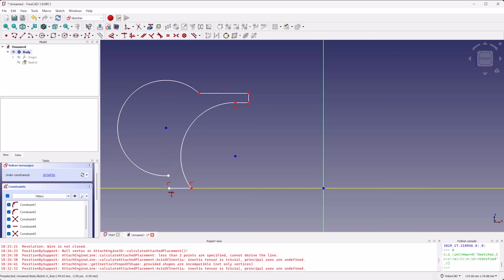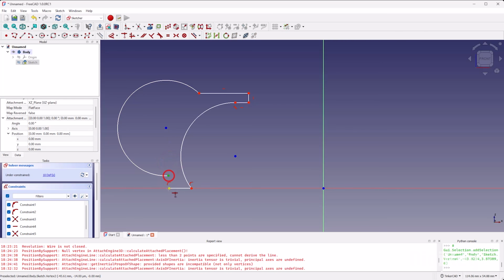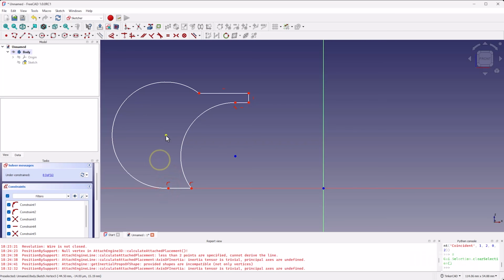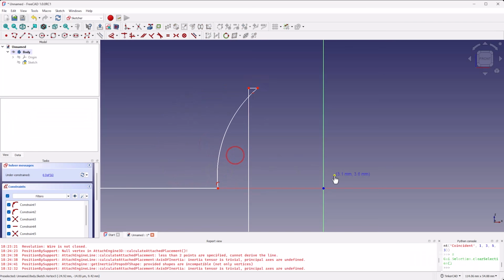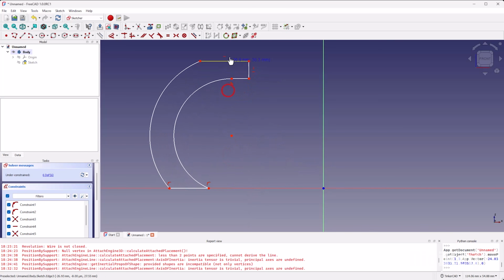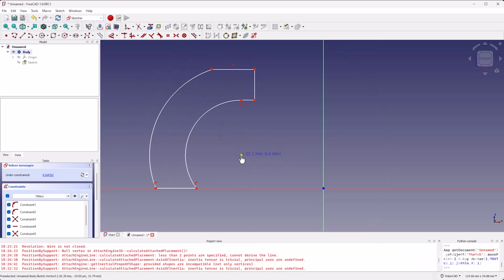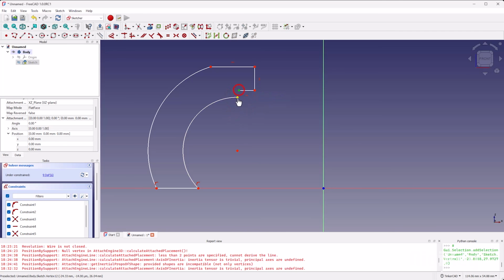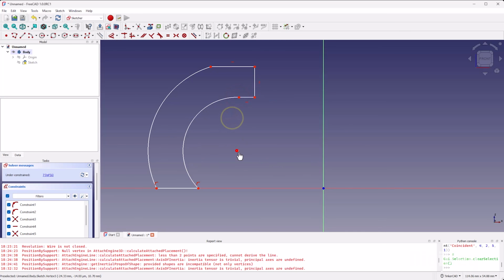So it looks like that's coincident to this axis. So let's make these two coincident. And we want to make these points line up. So make these points coincident by pressing C, making those 2 points line up. And we're going to bring this, it is not liking that. Let's make this a little higher. That's what's going on. This is tangent here. So click that, delete it. These two are now separated because it's not a red dot. So C, make these 2 points coincident. Right click to end that tool.